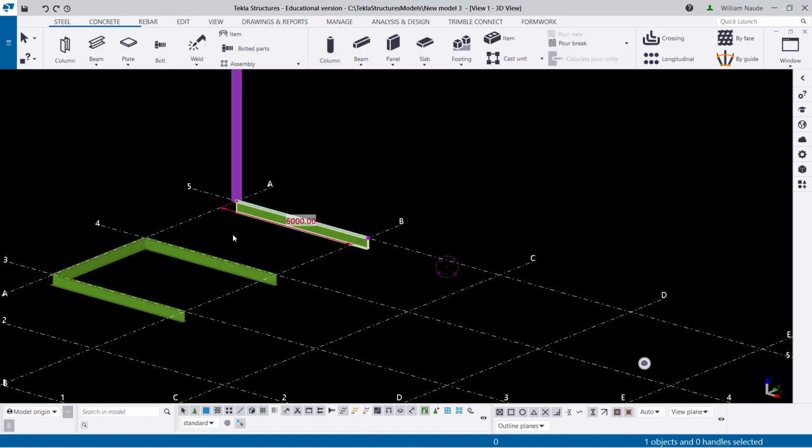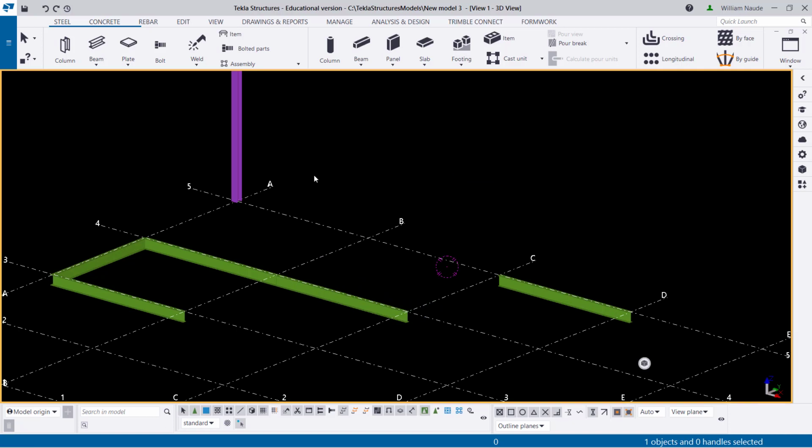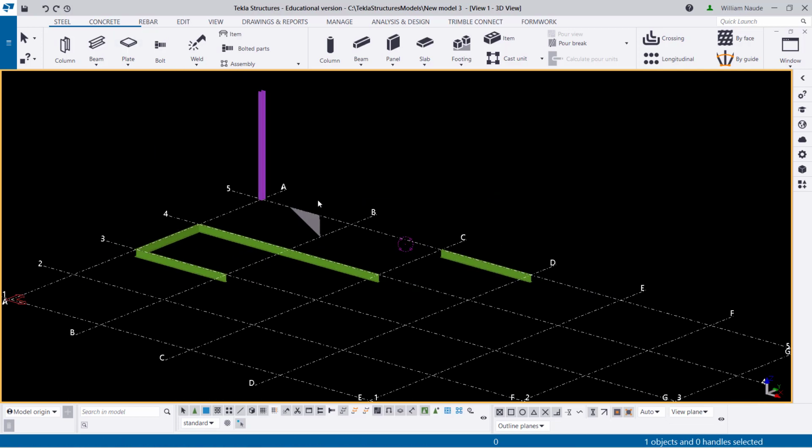So if I choose this one, I say Control C, I can choose my point and I place it down. If I say M, I can choose my point and I move it. And there we have it. Now normal P will be my contour plate, this function right here. So I'm going to choose my contour plate. There we go. There we have the different shortcuts already initiated and installed in our program.